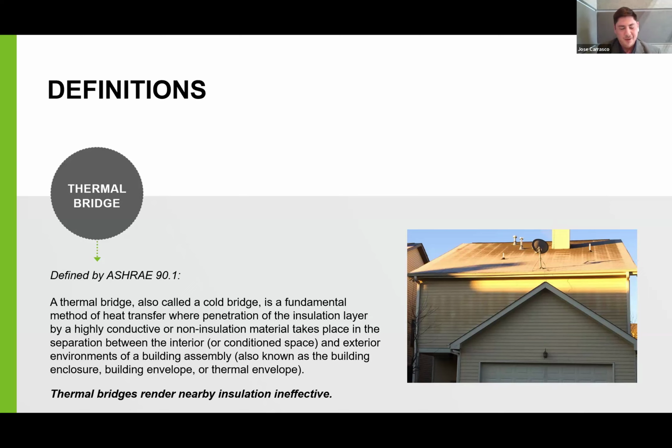This is important because the thermal bridge is really the number one killer of thermal efficiency in your insulation system. So keep that in mind again when selecting a continuous insulation Z-girt system. You're investing a ton of money up front in the insulation that you're buying for that project, and you really want to make sure by eliminating thermal bridging that you are getting the maximum efficiency that you're expecting out of that insulation product.